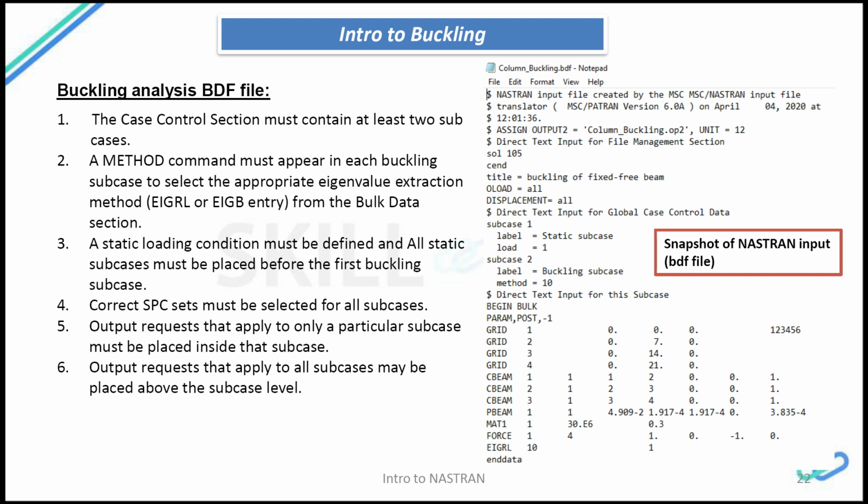And then correct SPC sets. SPC stands for single point constraint, which represents the boundary conditions, fixed and hinged, those kinds of boundary conditions. So all the SPC set numbers should match, and the output requests that apply only to a particular subcase must be placed inside the subcase.